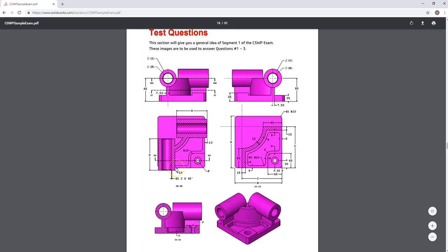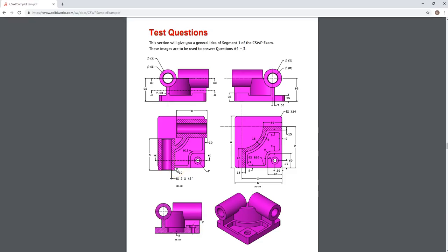Okay, so you actually have to start the dimension 10 out and then come in. Now, there's several ways to do this. You can do an A, B, or side 1, side 2 two-sided extrusion. But since we're going to use one dimension, and I want to make my life easy, I'm going to go ahead and create an offset plane on both surfaces here.